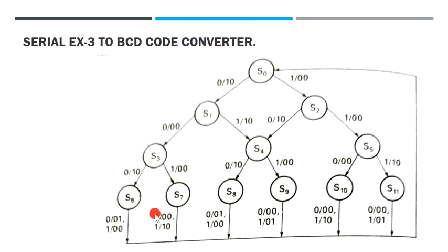So states S6 to S11 will indicate the reception of the third BCD input bit. After the fourth bit, all the states must return to S0. The output from the final state transition back to S0 will depend on whether a correct XS3 value has been received.